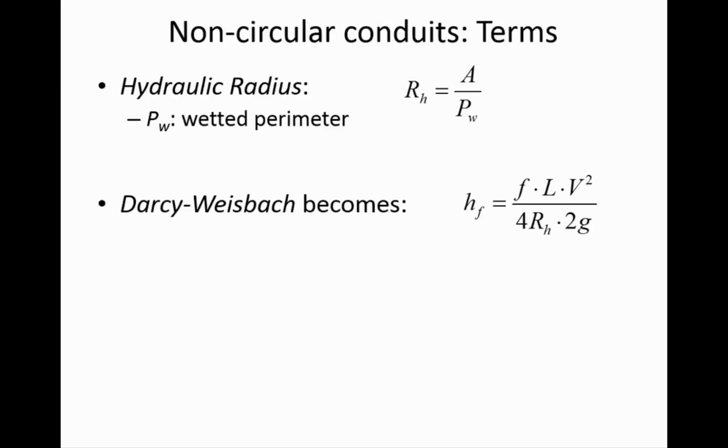D parameter. And that's related to our earlier observation that for a pipe that's flowing full, hydraulic radius is just D divided by 4. So for any enclosed conduit that's flowing full, we can make a substitution, we'll say that D is going to be 4 times the hydraulic radius, R sub H. All right, so that's what's been done here.